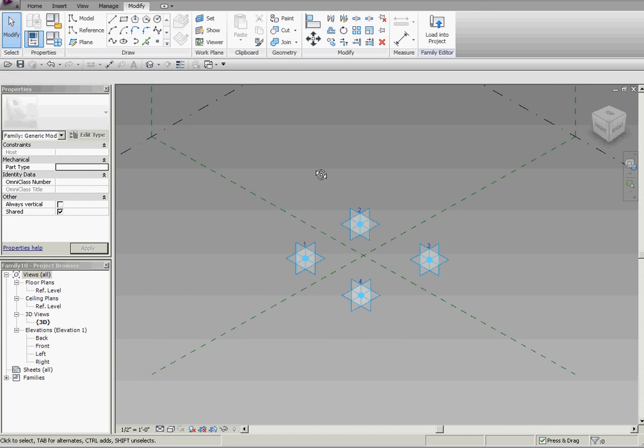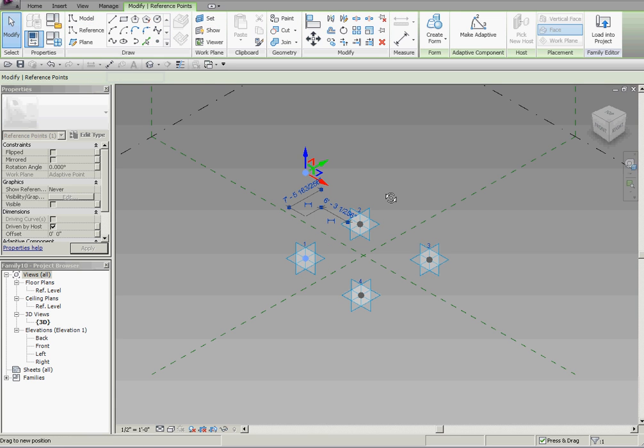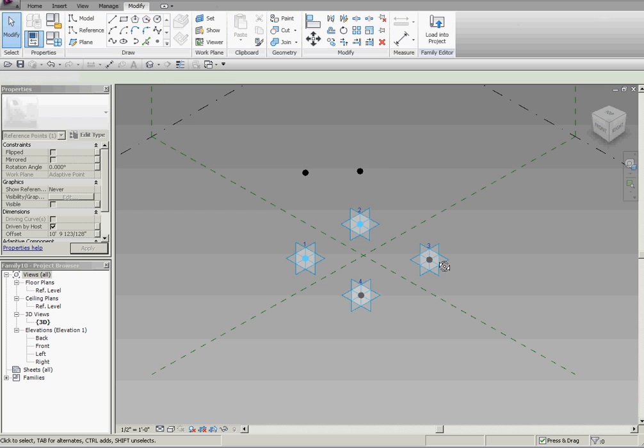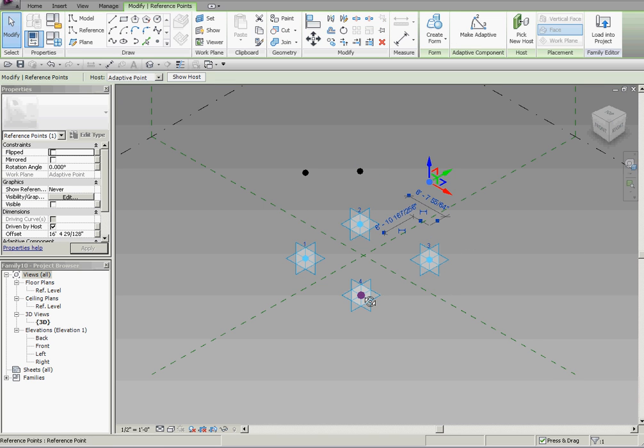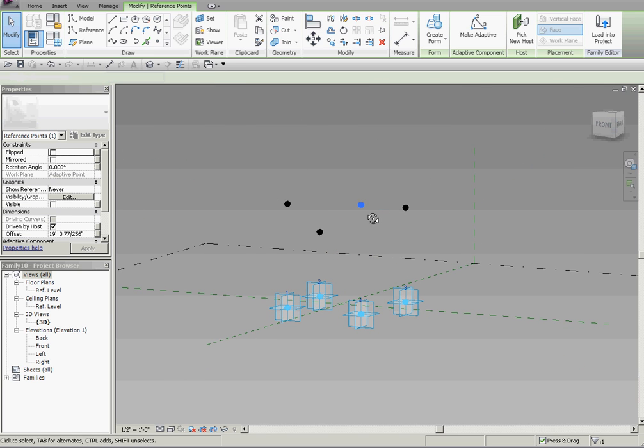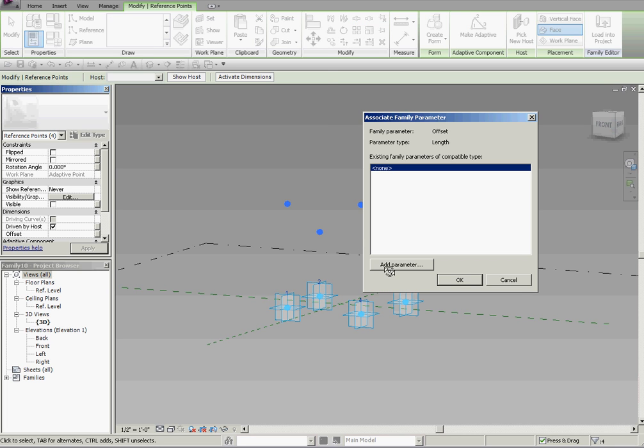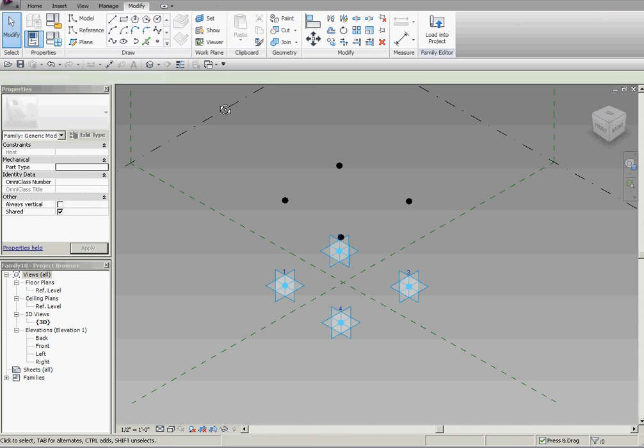1, 2, 3, 4. And I'm going to host points on these guys, which some of you have seen and tried. And this is just a nice way to get a particular kind of offset surface, which we're going to need to do this trick. And it just takes a second to set it up. We take each one of these points, we drag it vertically. I'm going to give them all the same parameters so they all sort of snap to attention at the same height. I'm going to call the new parameter H. And off they go. They snap to position.